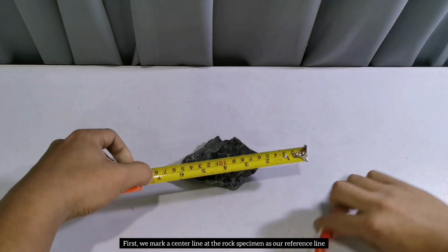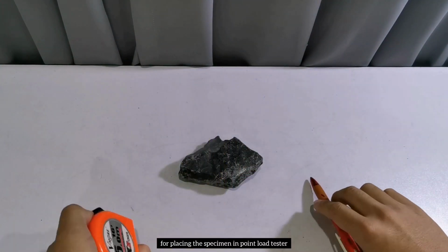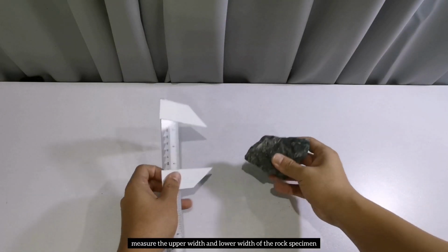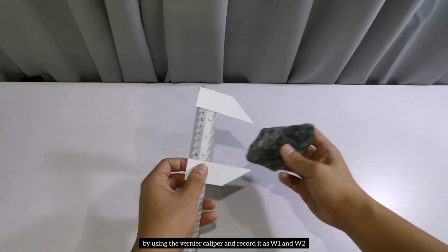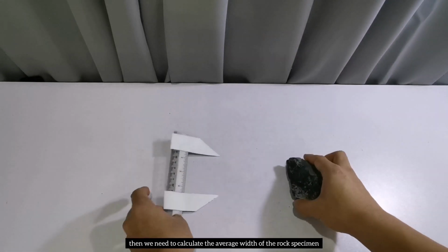First, we mark a central line on the rock specimen as our reference line for placing the specimen in the point load tester. Measure the upper width and lower width of the rock specimen using the vernier caliper and record them as W1 and W2. Then we calculate the average width of the rock specimen.